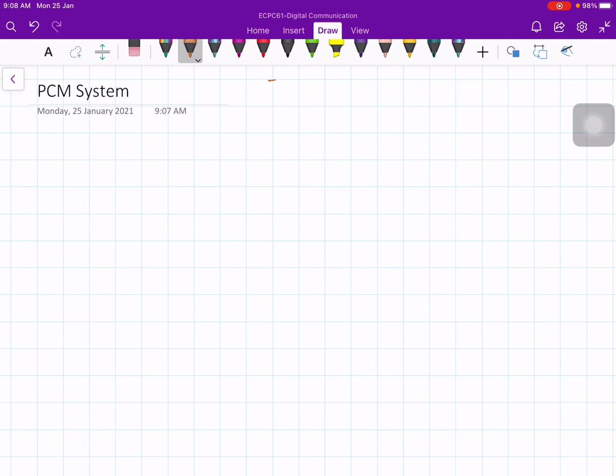The transmitter you are now quite familiar with, right? At the transmitter we have a message m(t), which must be low pass filtered. So you put a low pass filter with the cutoff frequency fc equal to, let's say, 4 kilohertz. That means even though your message signal contains frequency components above 4 kilohertz, you are not interested in sending those frequencies.